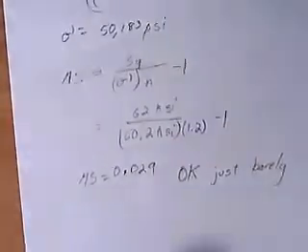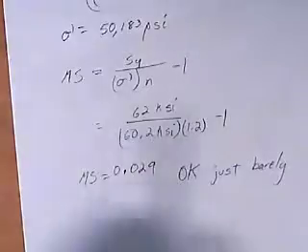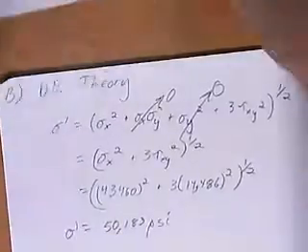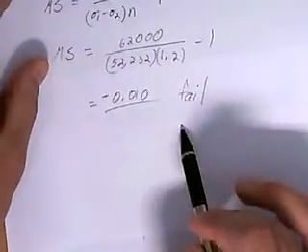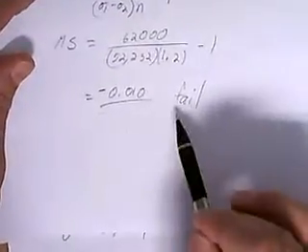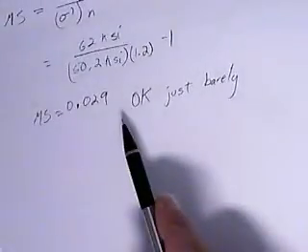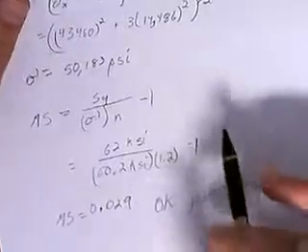So if you're looking at this, which one is more conservative, or how they compare, you can see that MSS theory is a lot stricter in that you have to have more material or better standard quality materials in order to be successful, otherwise it's going to cause you to fail, as opposed to DE theory, which lets you kind of get away with the very minimum, even though MSS theory doesn't allow you to do it.